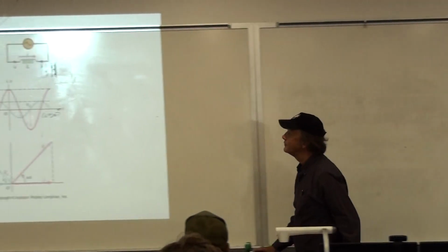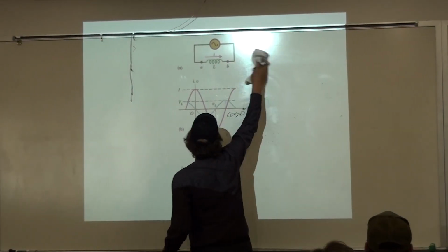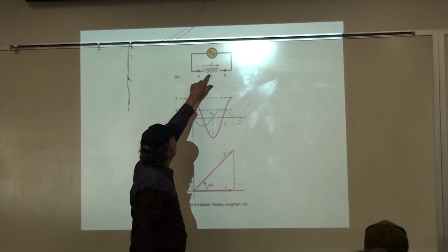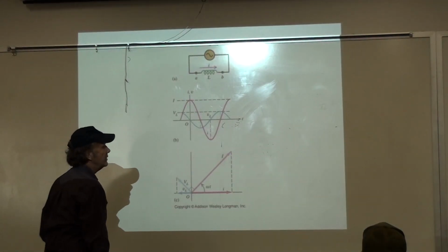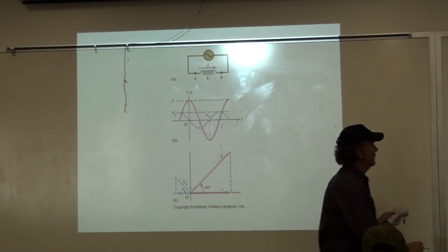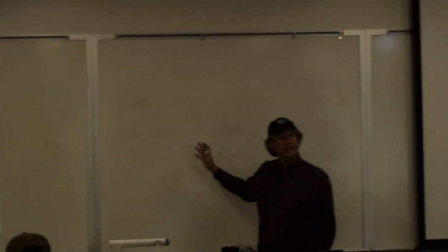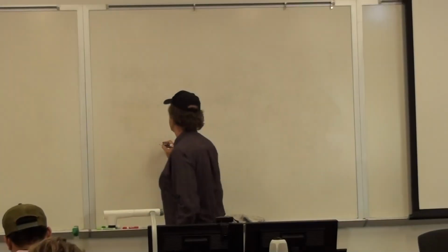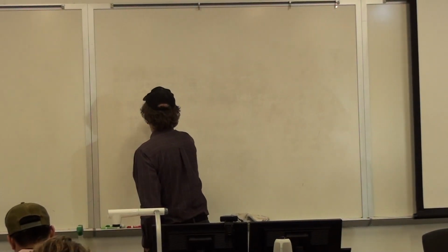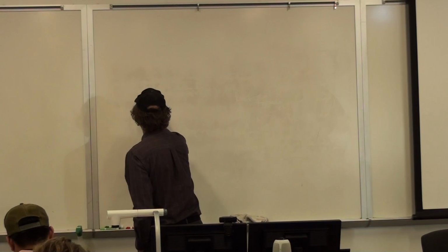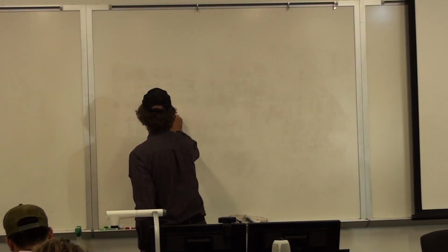Here's the inductor. So let's say that we want to store some energy in that inductor. How can we figure out how to do that? Well, remember that it's going to fight against us. And so it means that we're fighting the back EMF to prevent this from happening. So to build the current up, we've got to fight against that back EMF. And so that EMF looks like, well, N phi equals Li.